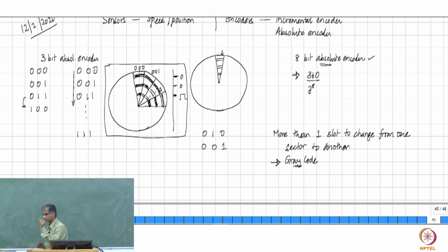Because if you are going to have small slots and an LED which is going to emit, and another electronic which is going to detect, and then if this is not completely well enclosed, if there is some amount of ambient disturbance, some sort of dust, and if it enters into this, then your encoder will stop functioning, right? So optical encoders have this difficulty that the environment has to be very good, or the encoder has to be very good, impervious to even small amounts of dust.